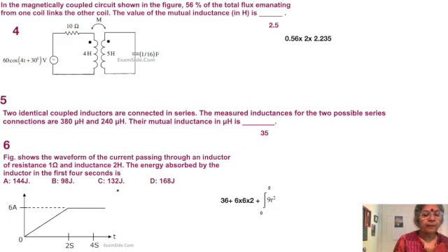So we have now one component wherein we are having the inductor, assuming steady state with 6 amps flowing through it. So we have half Li square. So we have the 36 joules. Okay, half Li square will give you the joules.